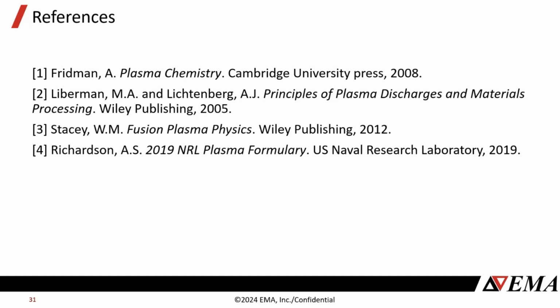And let's see, here's a longer question. If I wanted to reduce plasma down to a lumped parameter, could your particle-in-cell solver determine the impedance of the lump? And then it goes on to say, I'm interested in determining plasma grounding behavior. Are there any tools or methods to do this? That's a very good question. So they do report on the plasma conductivity, and you can use that to get a lumped impedance for your plasma.